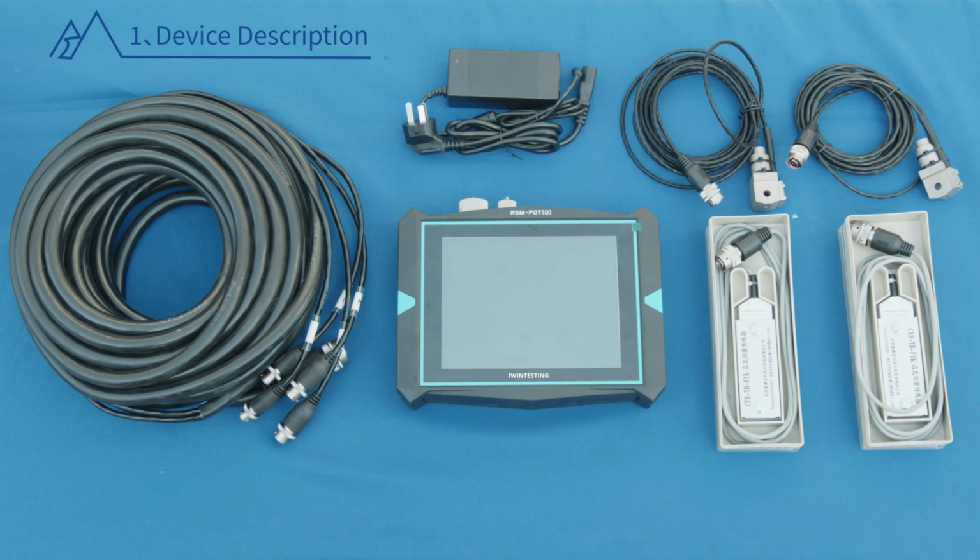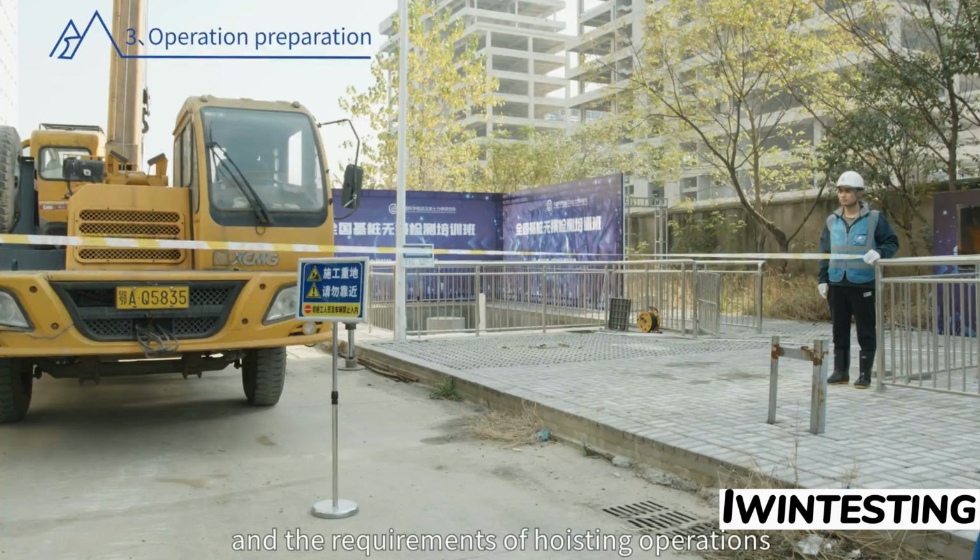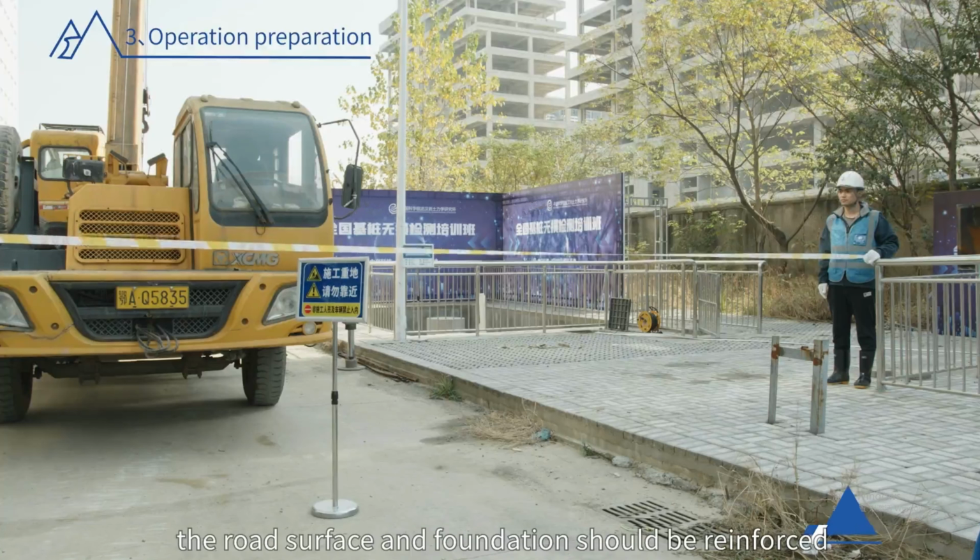The testing site should be dry and flat and can meet the traffic conditions of large hoisting equipment and the requirements of hoisting operations. If necessary, the road surface and foundation should be reinforced. During the test, there shall be no construction projects that generate vibrations around the site, such as dynamic compaction, vibratory rollers, large lifting equipment, etc. Excavate the soil layer where the sensor on the pile side is installed.